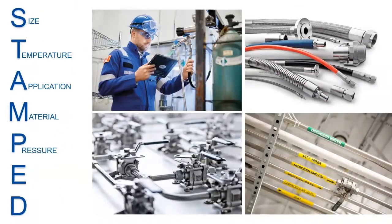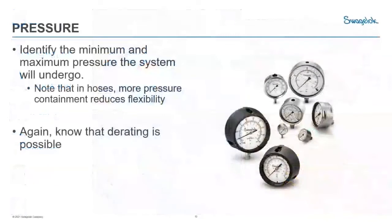The next letter we'll look at is P for pressure. When selecting a product, you want to identify the min and max pressure the system will undergo. So think about your normal operating pressure as well as extremes in both directions. What will the highest pressure be at your highest temperature and vice versa?